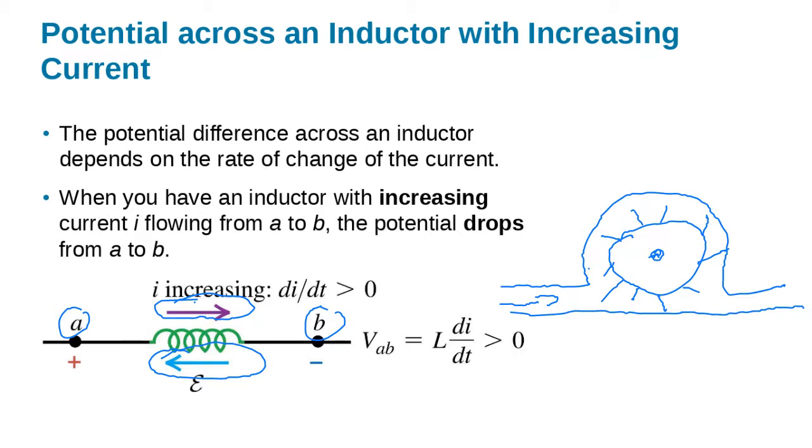So if we started flowing water through a circuit, pushing this water wheel around, and we put some pressure meter here, something that can measure difference in pressure between this point and this point, then if we say that this water wheel is ideal, so it doesn't dissipate any energy, it's got no friction losses, this makes it analogous to an ideal inductor.